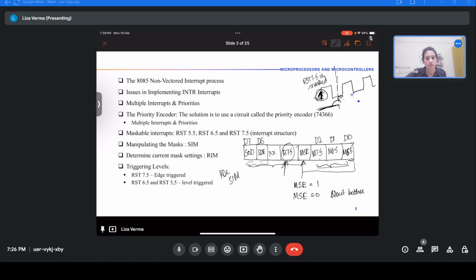But we want to have that provision to reset this interrupt pin, so that whenever the need comes, you don't entertain the previously occurred interrupt. You may choose for it to be zero so that you entertain the previously occurred interrupt, but there is a provision and you need it. You understand why you need it, right? So that is why we have this reset for 7.5. What else? Don't care. It can be anything.